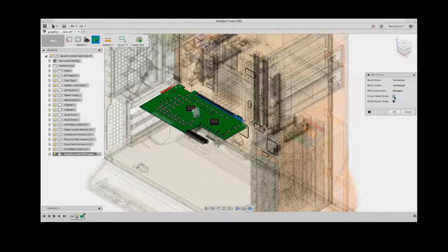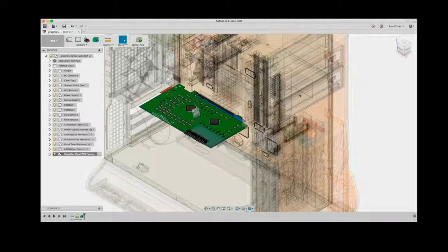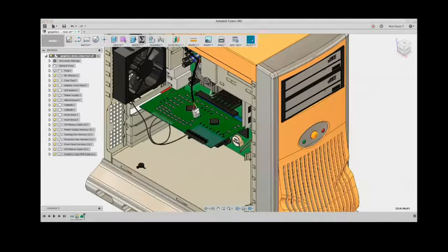So if we were to pull back to Eagle right now, with the Eagle board shape active, we'd see that component in Eagle would just be floating out in space, and then Edwin could actually edit the profile in Eagle. That's right. Because we've already done it, what we'll want to do is activate the Fusion board profile and then just pull that. Now, when I pull it, I'll see that cutoff taken away in Eagle, because he saves it and stores it in this.